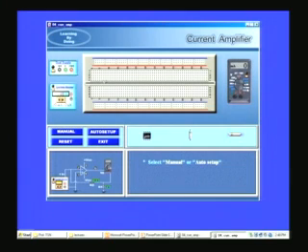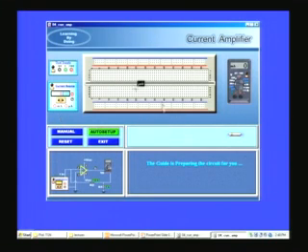So you have a breadboard here, you have a dual supply here, and you have a current source because you want to give a current input. You can give currents in the order of milliamperes or microamperes by increasing the values, and you have a multimeter here which is already set in milliamperes so that it can measure currents in milliamperes. You have the op amp and the resistors. Let me just form the circuit. So the op amp goes over here and the wiring is done.